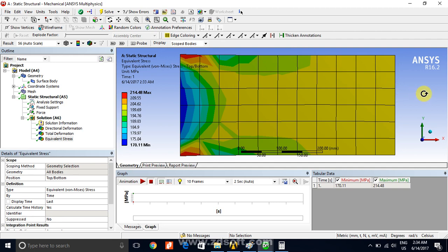In this case, force is applied here in this direction, and the shear stress in the plane perpendicular to this force is 0. So this plane is the principal plane, and the stress along this x-axis is the principal stress. It means this axial stress, which is P by A, is the principal stress. In the case of triaxial stress it will be different, but here this plane is the principal plane and this stress is the principal stress.